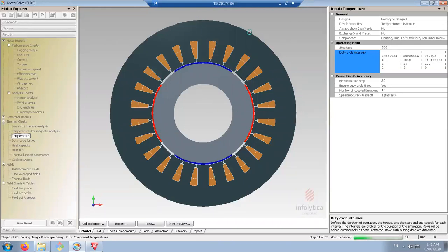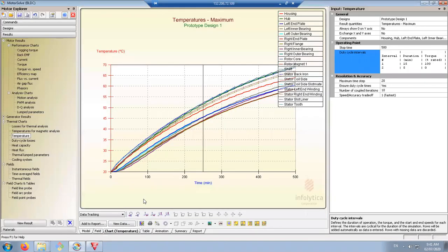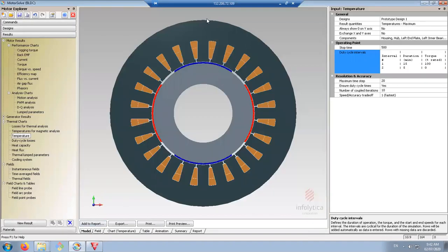So you can just take this part of the motor and ignore the other 3/4 and simulate that single part, I mean 1/4, in MagNet, this environment, which is going to be solved faster than this full model. Because in a full model, you have a larger number of meshes and unknowns.